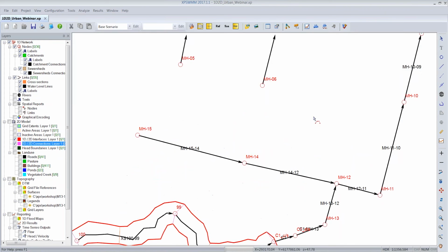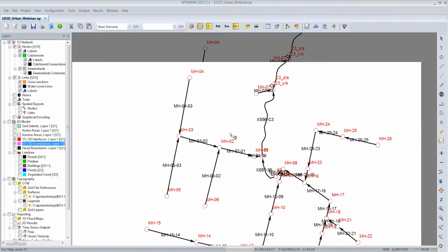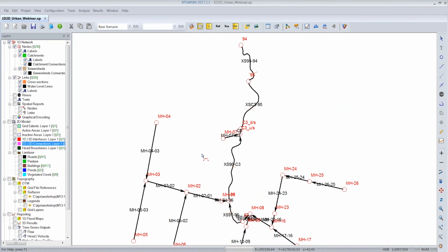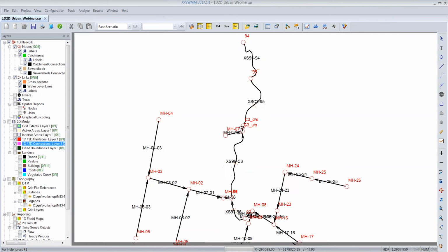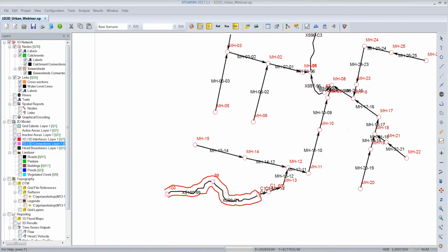And we need this, of course, also for the upstream part. So I could do the same up there. However, maybe for the sake of time in the tutorial, I will go to a finished model that has that done. So let me just go more completely down here and describe other things that we might want to do. Since there's an inactive area polygon here, there's not going to be any 2D flood result in plan view. But it might look odd to see no water in the channel in plan view.